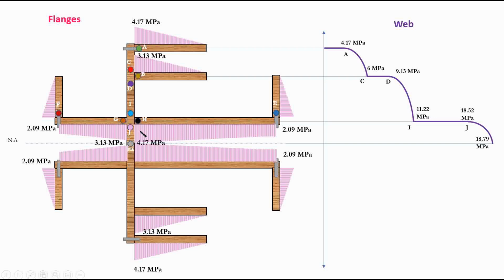And at the neutral axis, you see you have a distance here. So because you have a distance, we'll draw this as a parabolic distribution. And as we know, at the start our stress is 0, and then we move to the max. This is the peak stress at the neutral axis. The peak shear stress will occur at the neutral axis. And the rest will be symmetric.